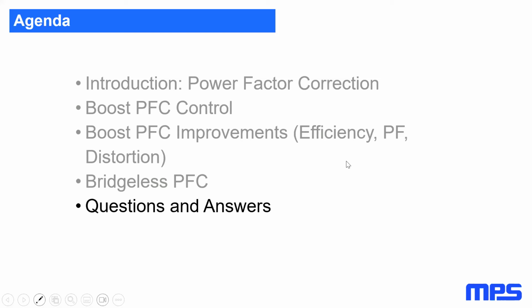Thanks a lot. The next one is, can you suggest PFC ICs that include triangular compensation, PFC control law? Okay, I think if you check the latest combo PFC plus LLC IC that we have, it should be the HR1230. I think this one includes that compensation. There might be more. I'm not completely sure off the top of my head, but at least this one should have it.